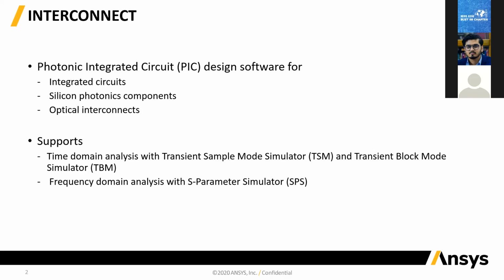In those cases, you create compact models for all the different pieces, hook them up as a circuit, and then you do a circuit simulation. Just like you do circuit simulation for electronic systems, you can do circuit level simulations for photonic circuits. And so that's where interconnect comes in. Interconnect is most widely used in silicon photonics, because in terms of photonic integrated circuits, that's the most matured field right now. But the same concept applies for any other photonic circuits as well. So if you have III-V based or silicon nitride based circuits, you can use interconnect to simulate those as well.